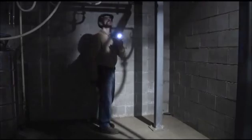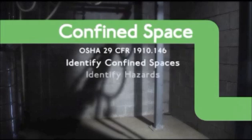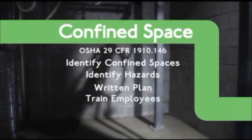An oxygen-enriched atmosphere also presents fire hazards. In a confined space, this hazard is increased. The Occupational Safety and Health Administration, or OSHA, has very strict standards that define procedures for confined space entry, including measures that can prevent fire hazards. The standard requires companies to identify confined spaces and their hazards, develop a written confined space entry plan, train appropriate employees to safely perform entry, and provide the tools and equipment for the confined space entry team.